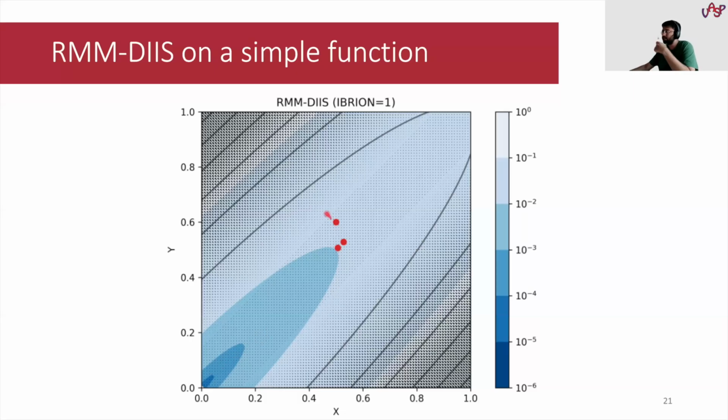And then the algorithm continues depending on the step size and all of the different parameters that you have in the model. But briefly, these 3 points at least hopefully illustrate the intent of the algorithm, what the algorithm is trying to do in context. Something to note is I've started fairly close to the minima. You may argue that the performance very far away from the minima may not be as nice, especially if your forces start to increase somewhere along the way. So you have a valley and a trough. This method will fail. So keep in mind, really use this only for things where structures are not terribly awful. This will work only if you're there or thereabouts. This is the best place to use this method.